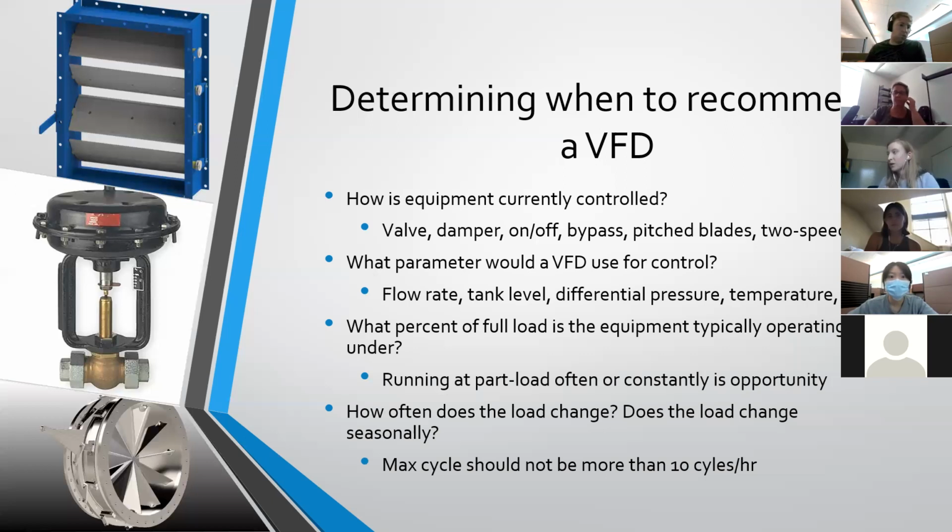Moriah, I'm going to ask you to elaborate on one thing. Explain to us very briefly what you mean by differential pressure. Sure. It can actually mean many different things, but here I was talking about differential pressure across the pump. If you have a pump or a fan, you're going to have some suction pressure coming in, a discharge pressure coming out, and the difference between those two is your differential pressure.